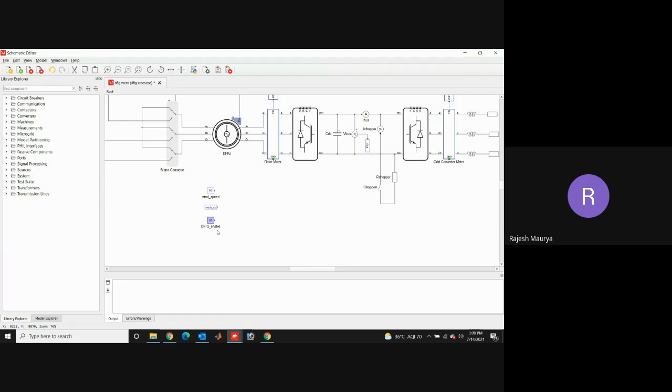Now I also require the state for both contactors, GSC_state and RSC_state. For that purpose also, I'll copy this From block and paste it. I'll change the name from mechanical speed to GSC_state and the scope to local, because I have taken local over there. Similarly, I'll copy the same From block and paste it over here, and the only thing I'll do is change the name to RSC_state.